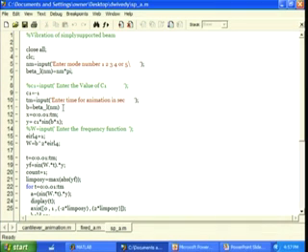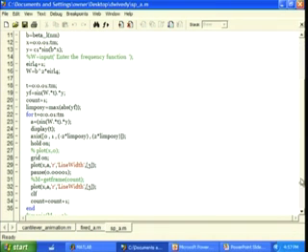For the nth mode beta L will be n pi, and taking EI by rho L fourth equal to 1, you can find the w function. This w is written in terms of yf, which is sin omega t times the mode shape C1 sin beta x. To simulate this, you just run it and check.